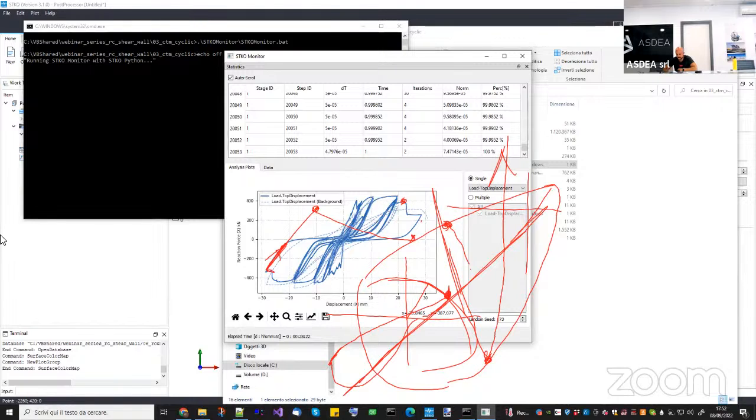And since you treat the entire stress tensor as an equivalent scalar, and you work in the principal direction, it means that you are not caring about the direction of the stress, the direction of the action. That's why when I say if it is damaged in one cycle, in the other cycle, even if the loading direction is different, the material model will be completely damaged because it works in the principal stress space. So you do not take care about the damage-induced anisotropy, which is something that we want to put also in the model. Yeah, I understand.